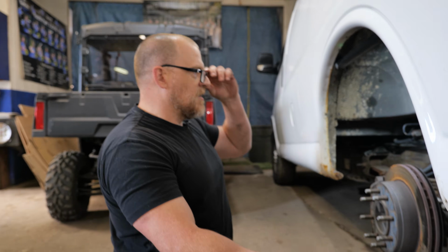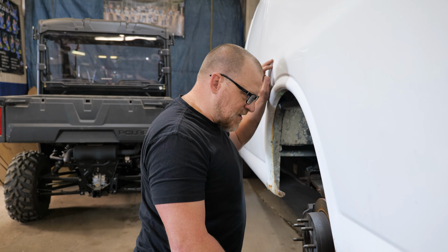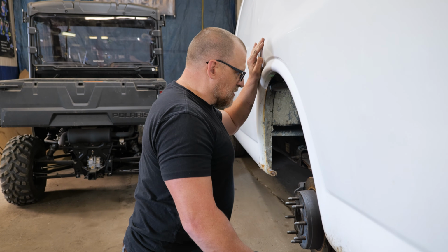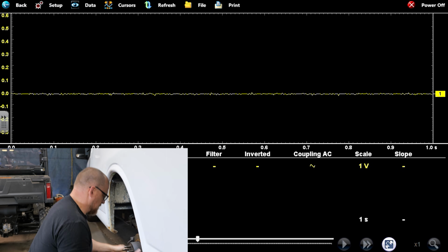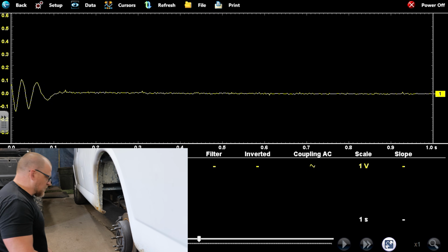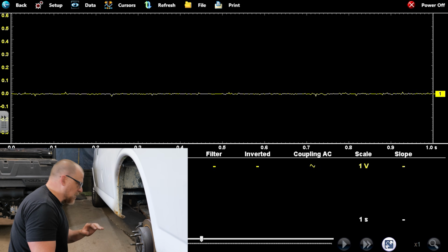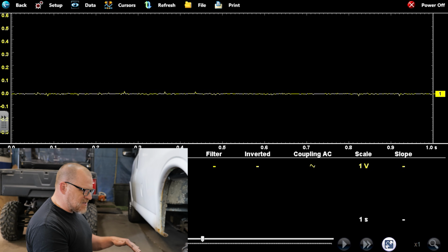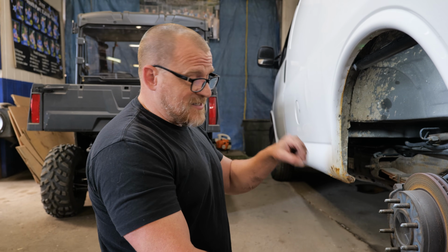So this is different than my truck. Now I'm confused on this signal in general. That should be a square wave, not a sine wave. I know I picked AC coupling, but that just blocks the DC constant. You'll still see digital signals on off on an AC scale.